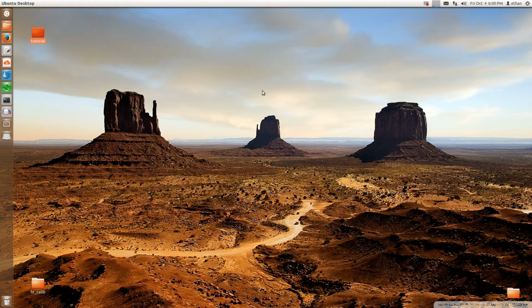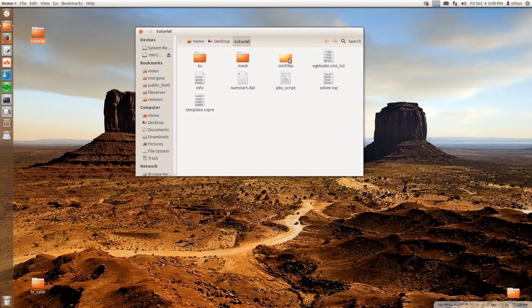Alright, in this tutorial I'm going to show you the process of running a flow simulation and how to prepare the necessary files to do that. The files that you need to run a simulation, there are 5 files, and in this particular example we're running a simulation with a model with 4 outlets, and we're going to prescribe Neumann boundary condition, which is pressure boundary condition for all the outlets.